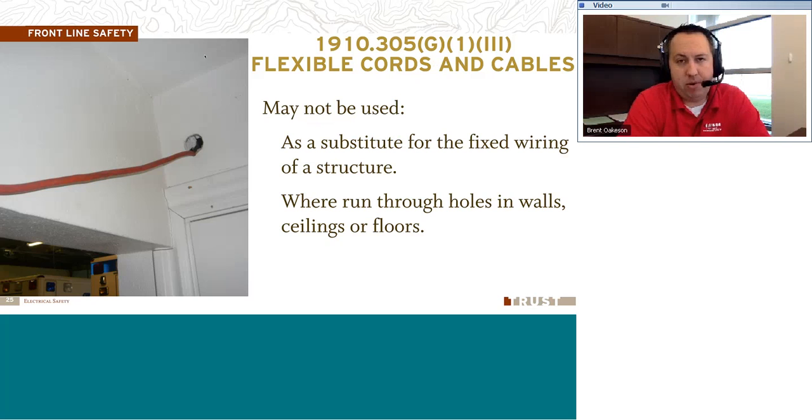Since they're temporary, they shouldn't be run through any walls. They shouldn't run through holes in the floors or any other openings. They should just be out in the open, plugged into an outlet, for temporary use. When you're done, you coil it up and put it away. Remember, it's not a permanent wiring situation.